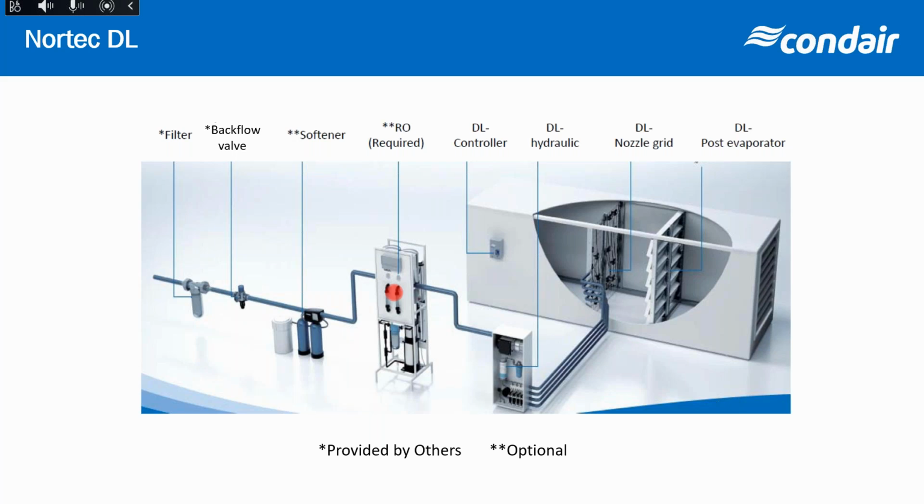So from there, you can see we have a little hydraulic unit there. I'll refer back to that in a second. The water is then under low pressure, as Nathan mentioned, anywhere from about 42 to 90 PSI. So it's a very benign water spray. We have up to 31 stages of modulation, and we have the manifold and the nozzles that we put together. All the modulation is done by us. And then we have atomizing in that area. So we're getting instant humidification, very responsive.